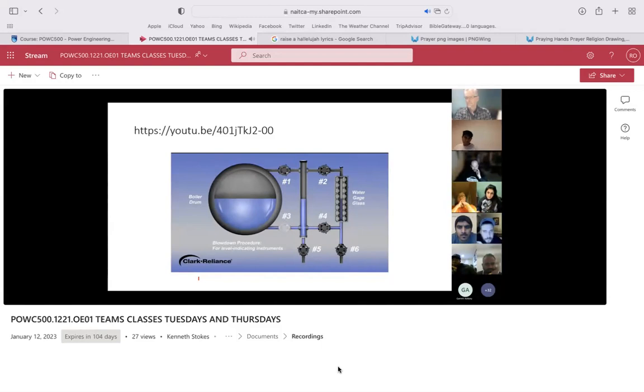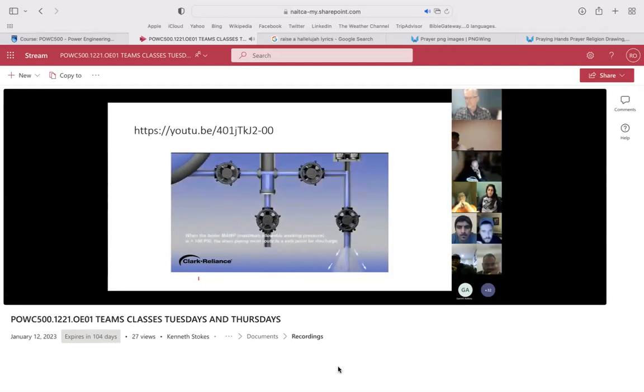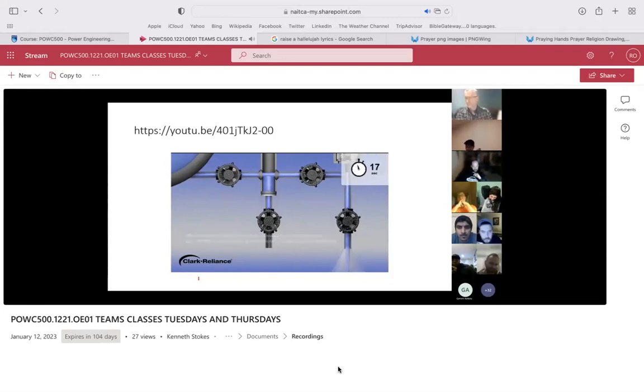Next, with water valves number 3 and number 4 in the open position, open the drain valve number 6, and the water will discharge. Water will be flashing due to the elevated temperature. This discharge from the water leg piping should be observed flowing out of the drain. The drain must be routed to a safe location, away from the operator. The drain piping may be routed to a condensate tank or a location away from the instrument, which may require a second individual in order to validate the flow.